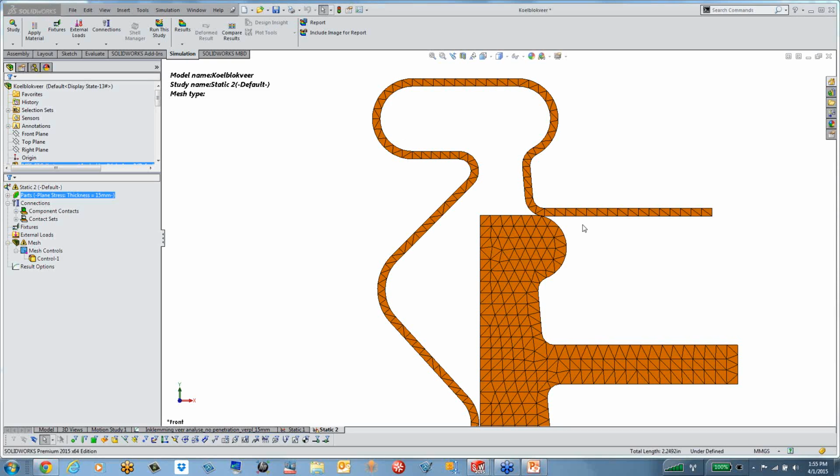So the second question is, why not 1/4 of this model? It has 2 planes of symmetry, and that's a great point. Absolutely, you can take 1/4 the model. Because it does have 2 planes of symmetry, and in fact 1/4 the model can actually be a much better option, because you're just analyzing less. That's going to dramatically reduce your meshing time and hence your solution times.